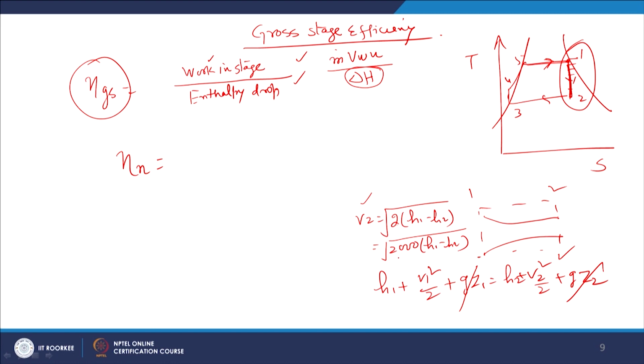So that is the enthalpy drop. Now what part of this enthalpy drop is being converted into kinetic energy? Because the nozzle has some internal frictions and internal losses also. And heat transmission to the surroundings cannot be denied, though it is negligible in the case of a nozzle. That is why we consider flow through a nozzle as an adiabatic flow, because the control volume remains inside the nozzle for a very short duration of time.